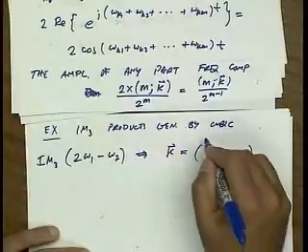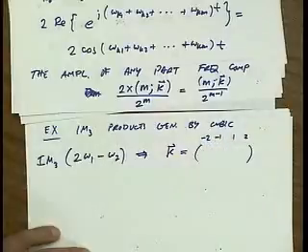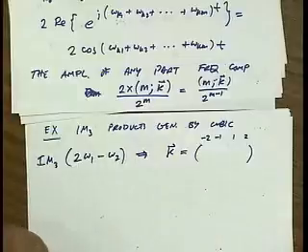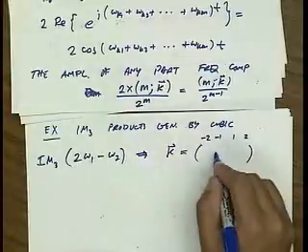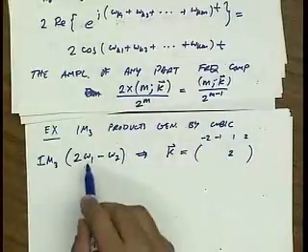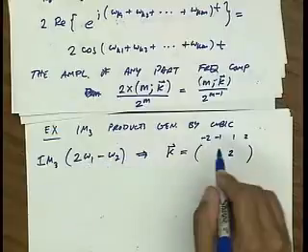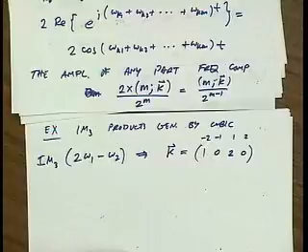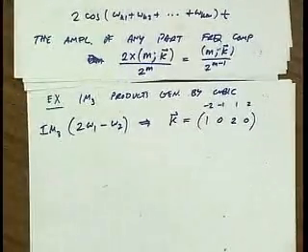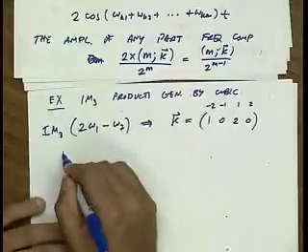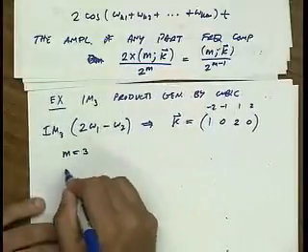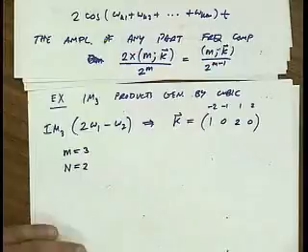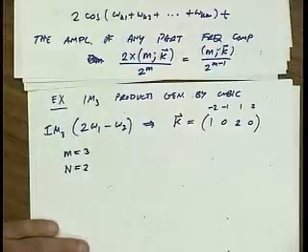IM3 product, and I write down my columns here, which tell me which frequencies I'm interested in, and we did this already. This has 2 frequency omega 1 and 1 frequency minus omega 2. So this is my k vector. Okay? Everybody see where that came from? Yeah, good. Now m is equal to 3 and n is equal to 2 for a two-tone test, right? I should have said that first.